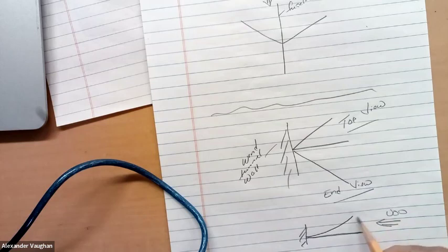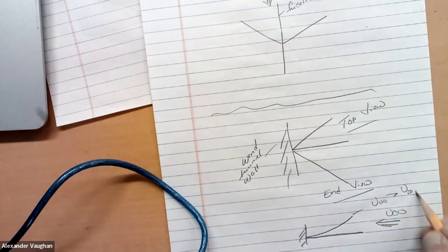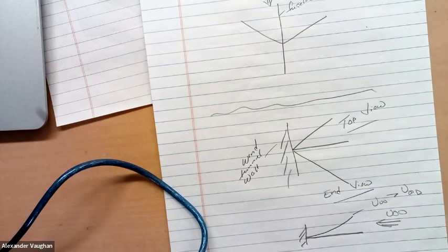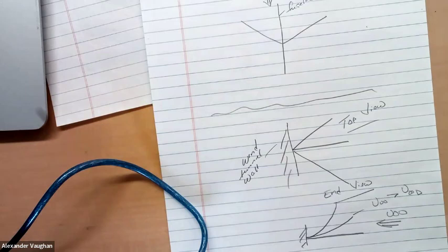Okay, this is when I'm beyond the divergence flow velocity, which also corresponds to a certain value of dynamic pressure. And then as I go to larger and larger values, it just keeps bending more and more until I break it. So it looks like a parabola, basically. Is this incorporated in the alpha E term? Yeah, this would be alpha E, but remember our linear model